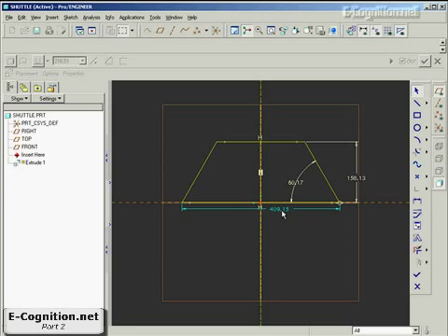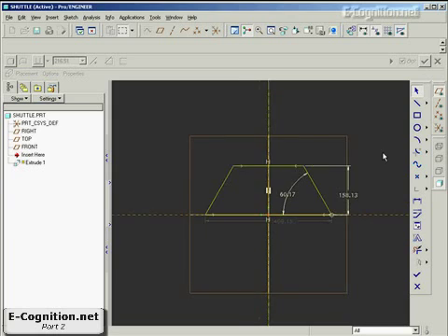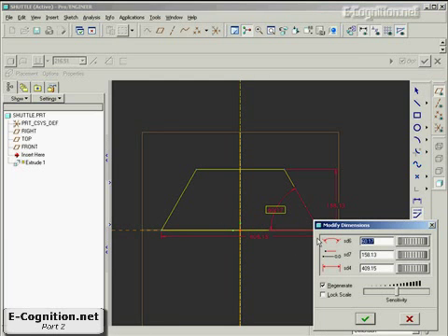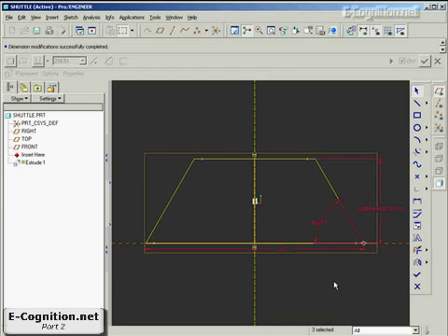3/4. I forget exactly what it was. I think it was 1 inch. But we want it to be 1, not 400. If I modify this from 400 down to 1, this sketch is going to turn inside out. You've probably run across this before, where you want to change all of them at the same time. Well, watch this. Pick them all, use the modify, and I want this 400 here to be 1. So if I choose what's called lock scale, I can change that one to 1, and it'll apply that ratio to all the others at the very same time. Pretty neat.